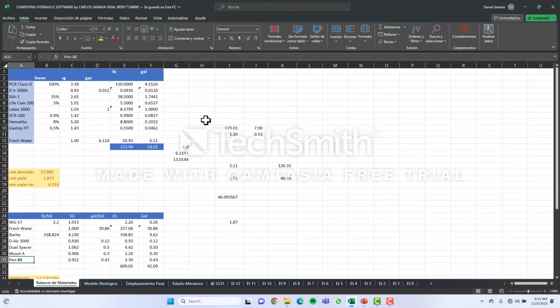Of course, first of all, we need to design the fluids that we are going to use in the liner production cementing operations. That means we need to calculate and design the cement slurry, what type of slurry we are going to use, main slurry, lead slurry, the density, the rheology is very important.